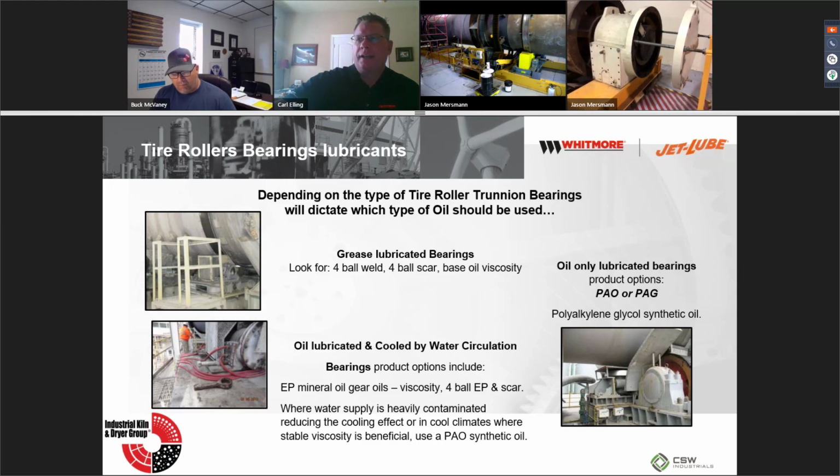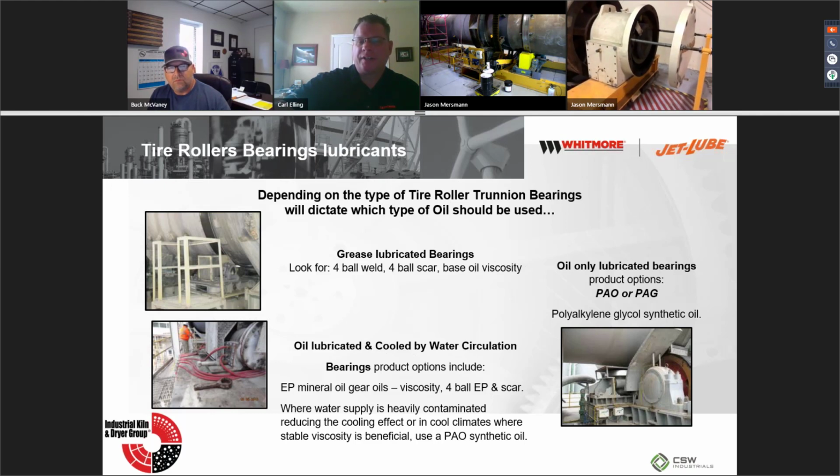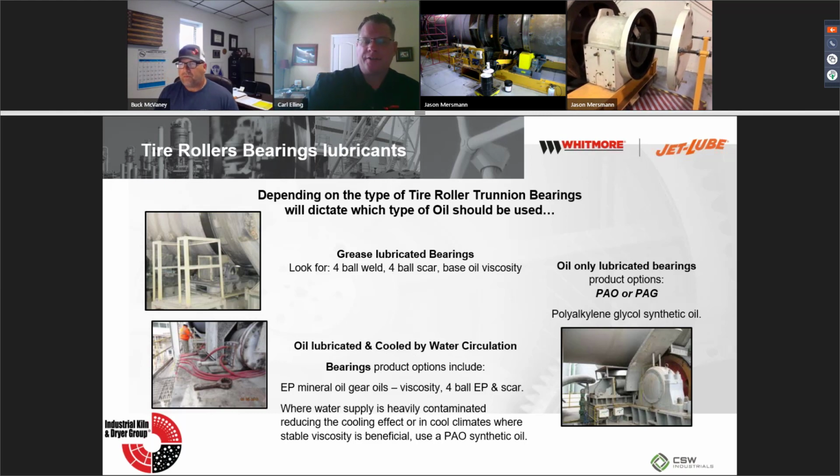And if you've got water in your oil, I typically will use a hub system, and you've got a bowl that you can put on the bottom there. You can drain the oil from that, but you can also quickly see visually, without opening up the unit, if you've got oil in or water in your oil. So it's a good visibility piece that we can add on there for reliability. We'll be adding that for future university classes. It makes maintenance a lot easier and quicker as you're doing your weekly audits, if you will.